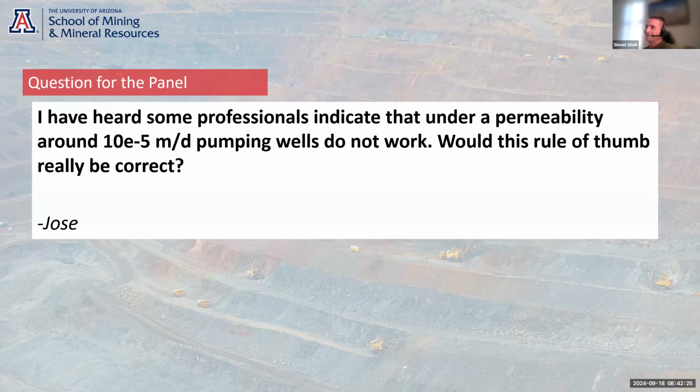How is it coming in? Is it through porous media? Is it coming through one fracture? Is it coming through a fracture system? And so assigning a single hydraulic conductivity to a single borehole, for example, from a single pumping test or something, just doesn't describe how the system works. It's a very crude method for understanding the hydraulics of a system.